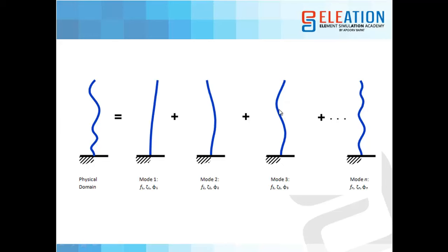and we try to see which mode is giving what type of deformation. Apart from that, as some external force is coming in the same direction where it is getting deformed because of the vibration, say for example, if in this particular zone my forces are coming in this direction, then it is already buckled because of the vibration, and if some external force comes in this direction, the buckling will increase drastically. So this component will fail in this particular mode.